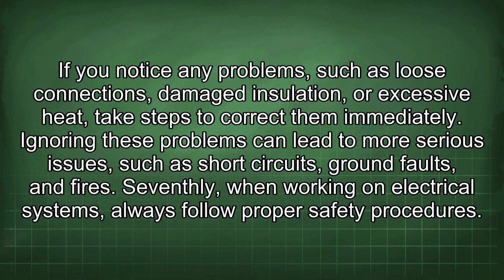Sixthly, regularly inspect electrical boxes for signs of overcrowding or damage. If you notice any problems, such as loose connections, damaged insulation, or excessive heat, take steps to correct them immediately. Ignoring these problems can lead to more serious issues such as short circuits, ground faults, and fires.